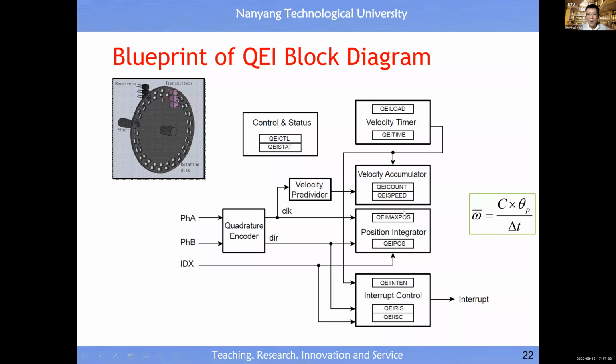Then what is the maximum position? Because this is to set the overflow. Let's say I only measure the maximum position from 0 degree to 360 degree, right? Full rotation. Go beyond that, then consider it 0, reset to 0, right? Something like that, to set the position limit, right? And just from the name of the register, you see how to operate it, all right?